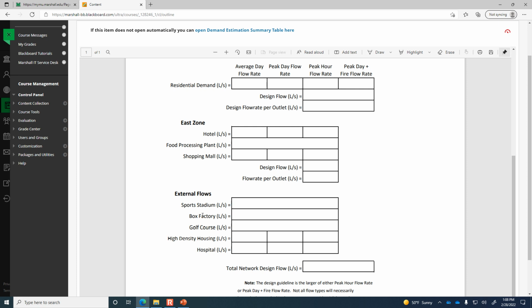If you think about it, what they're suggesting is that the water is always on at the golf course. And so the pipes wouldn't be big enough to deliver the amount of water that's needed if the irrigation period is a shorter amount of time. So I'm not going to tell you how many hours you should irrigate. I'm going to let you reason through that. But what I will say is, don't assume that the sprinklers are always going at the golf course. That would be non-conservative and bad for the game.